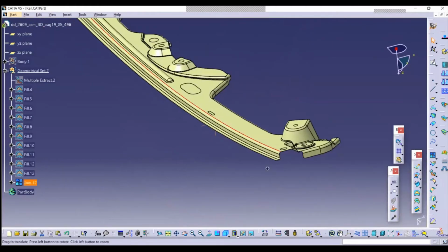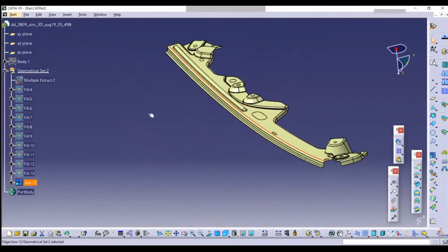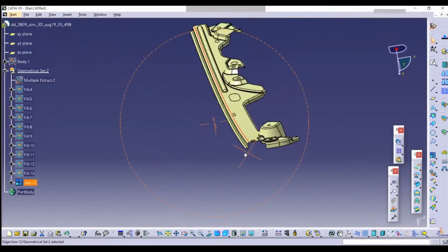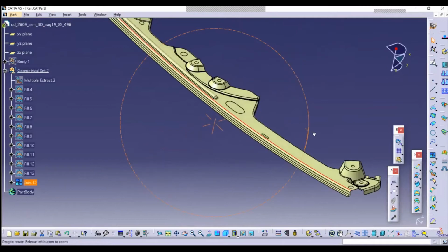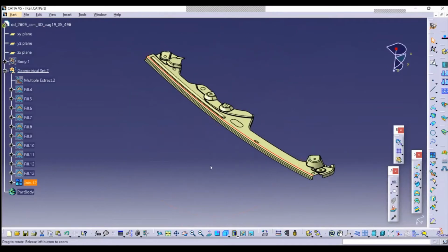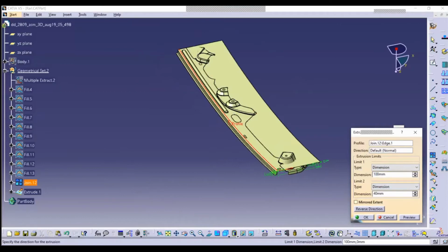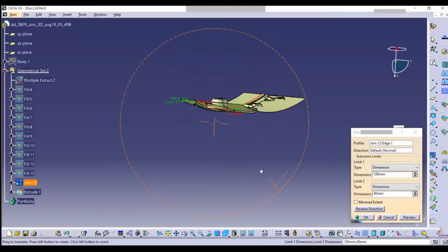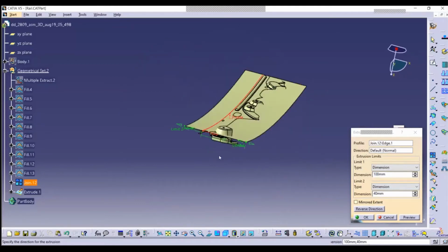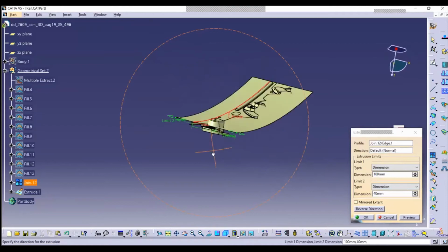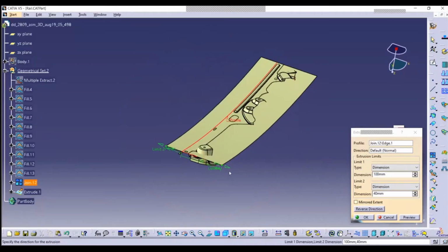So again, we're going to look at using CATIA functionality. I could use this edge, for example, as the curvature, and I could extrude this edge and then extrapolate it to make it larger than what the developed or unfolded part would be. So again, using CATIA functionality, I can simply choose the extrude function, and then I can choose my directions as well as define my distances. So maybe something along the lines of this. So something like this. So right now, sort of in the X direction, I have a surface that's extended larger than what the developed blank or unfold would be, the flat pattern.